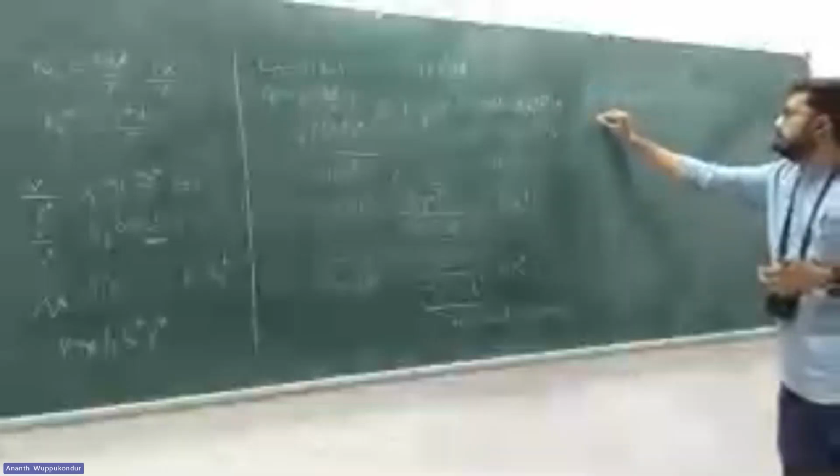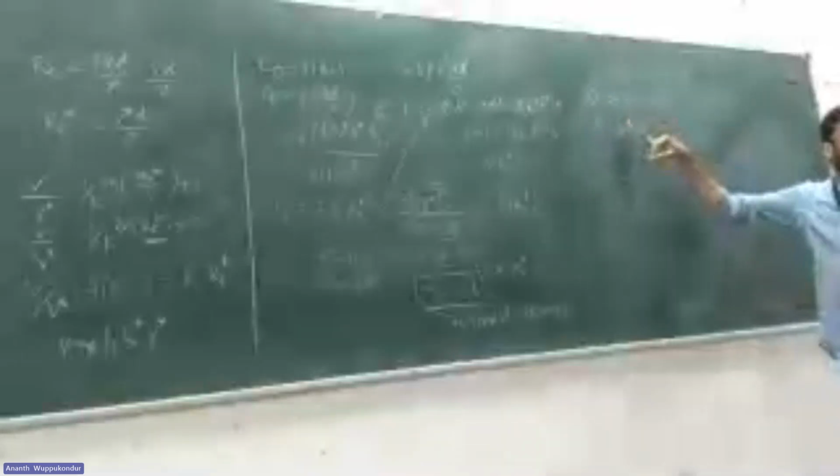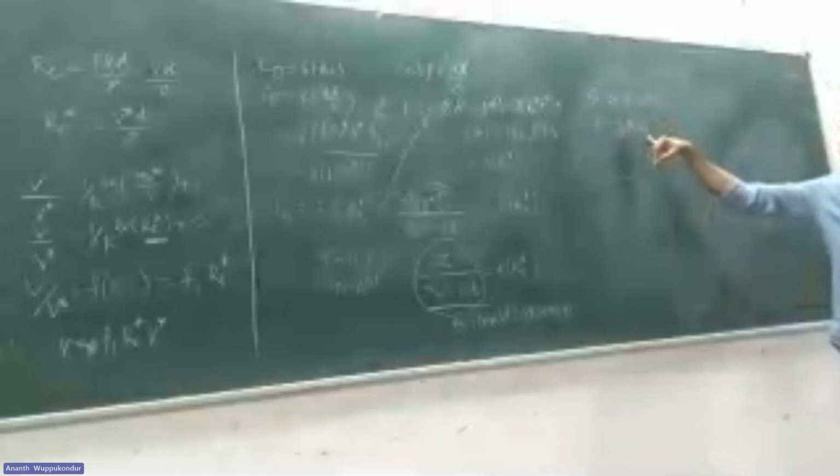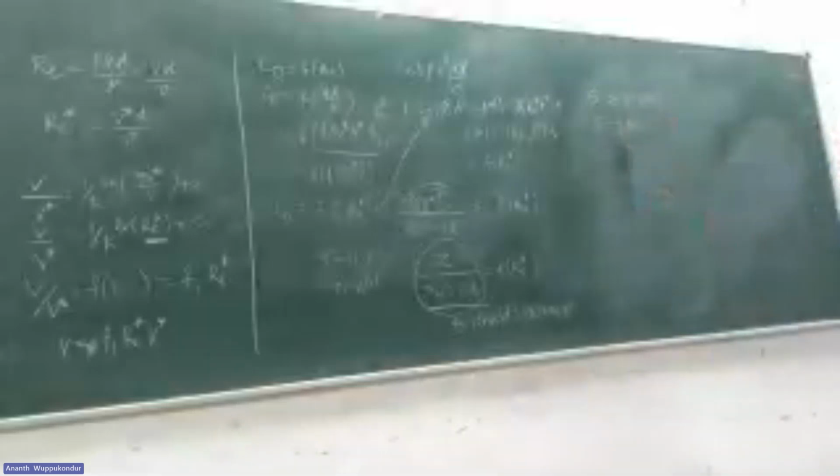And what if theta is just 0.056? So theta equals exactly 0.056. Limiting condition or the critical condition when the sediments will just start to move. So the sediments will just start to move when theta hits 0.056.